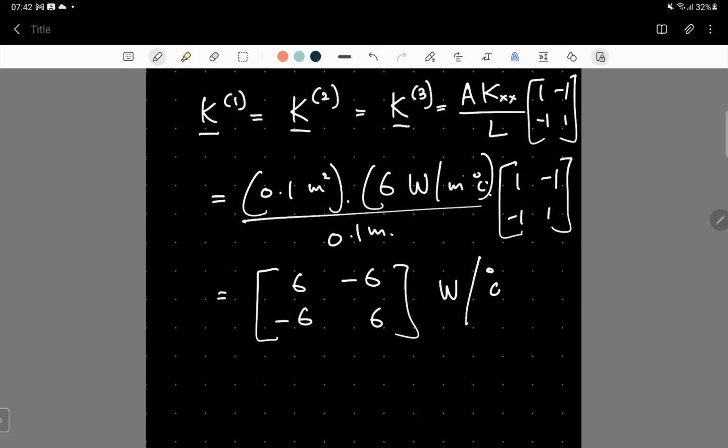We know that K4 is also equal to K1, because there is no convection taking place, since there's always a set temperature on the left hand side and a heat flux on the right hand side. So it is only the conduction which governs. So basically all the elements have the conduction term corresponding to this heat transfer problem.